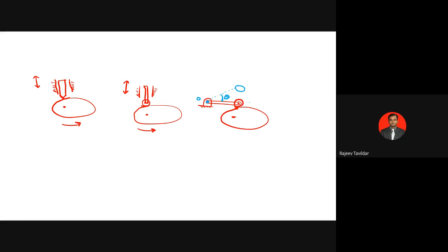Theta is the maximum angle with which the follower can oscillate. Oscillation is always given in terms of the angle. So the roller follower, I can make it with a reciprocating arrangement, as well as with the oscillatory. Whereas for the flat faced follower, I have to ensure that it has only vertical displacement. You cannot rotate this flat faced follower so that it can have the oscillatory motion.